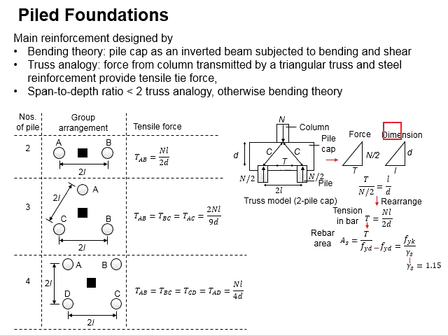The triangle will be in the form of d versus L. And it is assumed that the force generated within the truss here is proportional to the dimensions. That means you can use the dimensions here for you to predict the tensile force generating in the reinforcement bar.